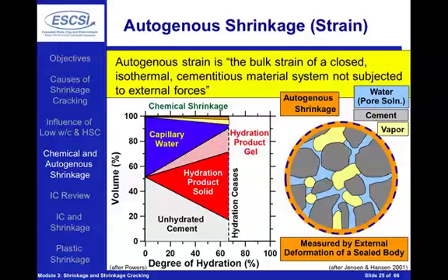Now, as I mentioned, the autogenous shrinkage is going to be a portion of the chemical shrinkage. So what is the remainder of the chemical shrinkage going to be made up of? Well, we know there's going to be a total volume reduction. However, after some point, the cement particles begin to impinge on one another, and the total external volume change can't be equal to the total volume change that's happening in the system. And what we will see is vapor-filled spaces starting to form inside of the matrix. These vapor-filled spaces, shown here in yellow, will give rise to this idea of self-desiccation happening in the system.